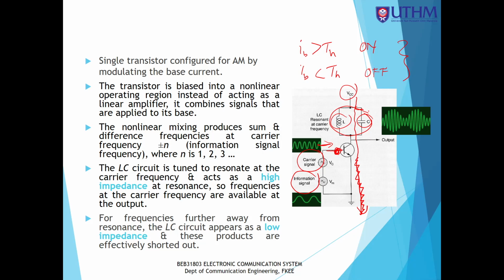Okay, during the negative cycle of the mixing input, the LC tank circuit will resonate or discharge, which will produce the other half of the output signal. So during this process, this circuit will produce a complete double sideband full carrier waveform.